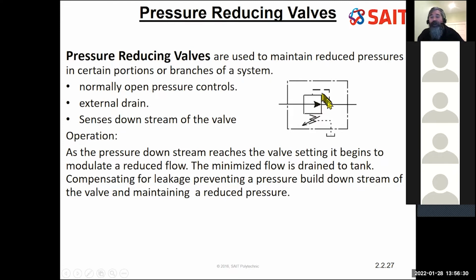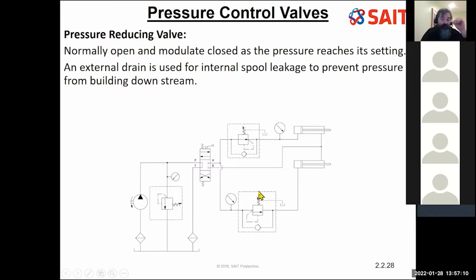It's going to require a drain to operate, and looking at the details inside that valve, you'd be able to see why that is the case. This is at the bottom, and it's drawn off the spring side, sometimes from the spring, sometimes just from the box on the spring side, to indicate a small volume of fluid, no more than a cubic inch per second, often less, is going to be required to escape through a drain in order for this valve to operate. If you don't connect this up, this pressure reducing valve locks in the open position and does not reduce the downstream pressure. So here's a use case for it.